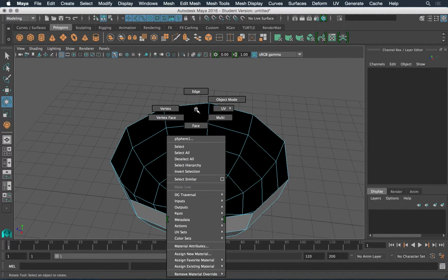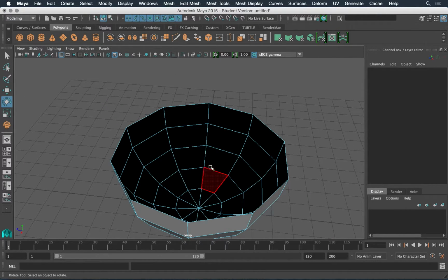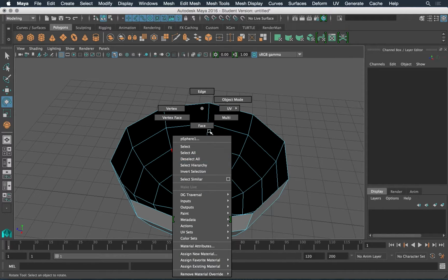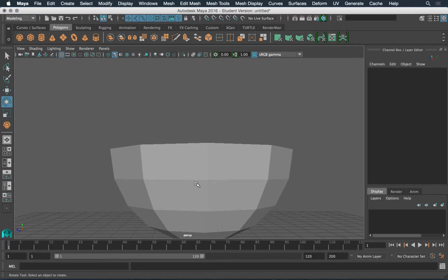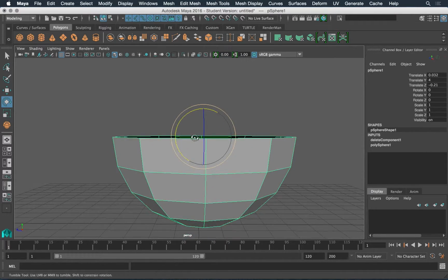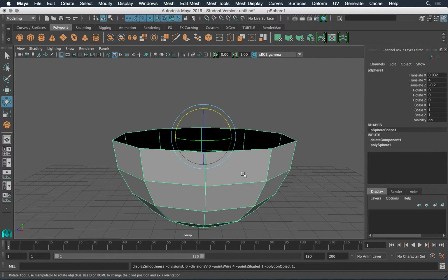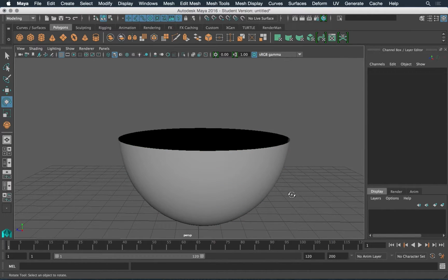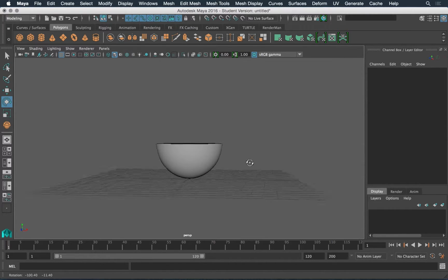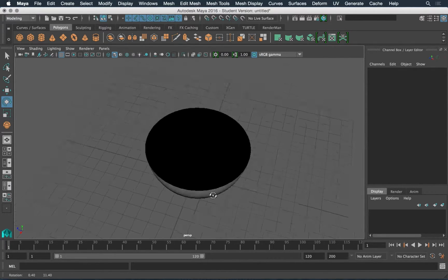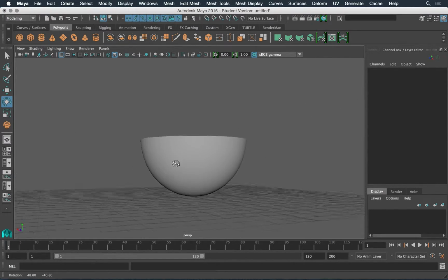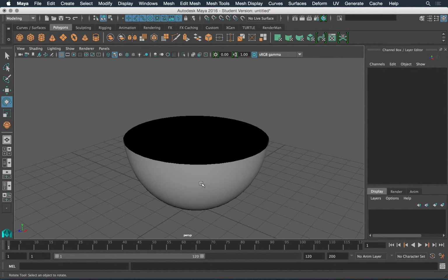And remember, if we go back to object mode, we're going to be switching a lot back and forth, just really get in the habit of right click and know which one's where. So object mode, and if we click on the object here, remember 1 is normal and 3 is smooth. So on 3, if we click off, it's actually a very smooth result, right? It's pretty nice. We don't need those 20 edges, 20 faces, subdivisions to get us going. Okay, we can stay really simple.